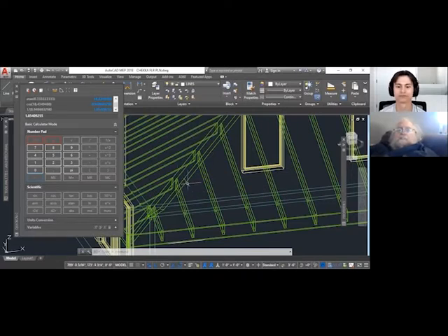And let me tell you why I use the long point. The long point is a convenient place to hook your tape measure. We could be talking about the center, or the short point, but I always use long points when I'm talking about jack rafters, and it's only because it's convenient.